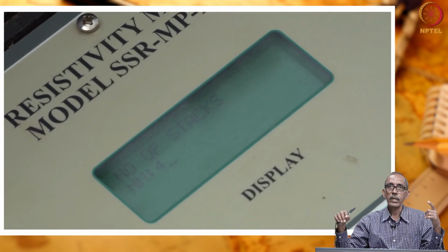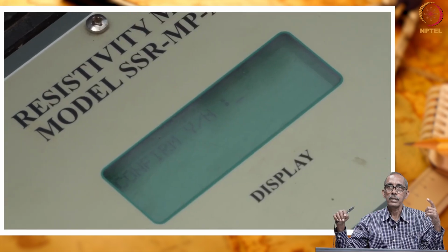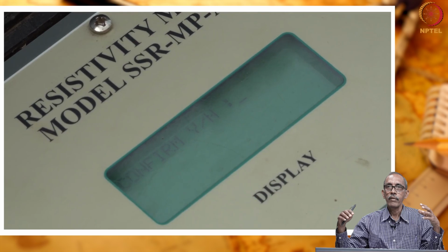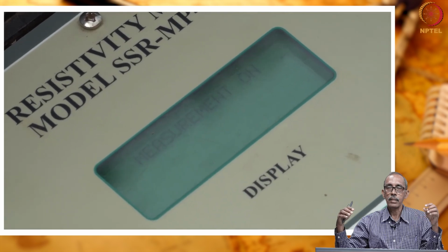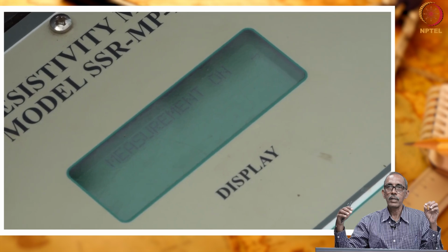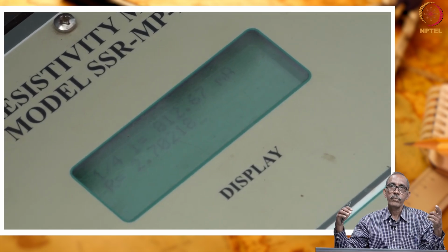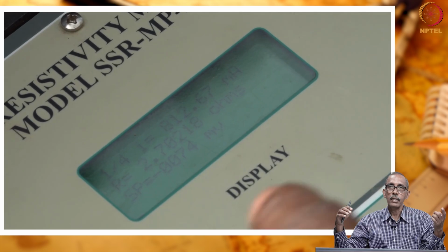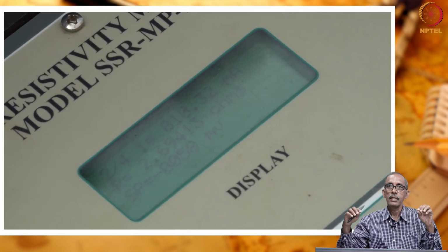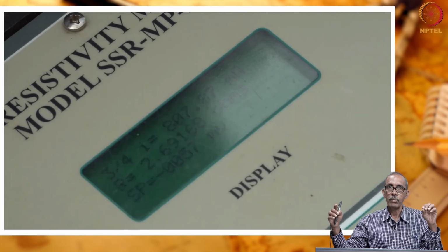Before that, we can also set the distances of the electrodes in the resistivity meter, so that we need not carry out any calculation. That means the distance between A and B are fed, as well as the distance between M and N, actually indicated at the instrument. We set the distances beforehand, then carry on with the measurements, right.